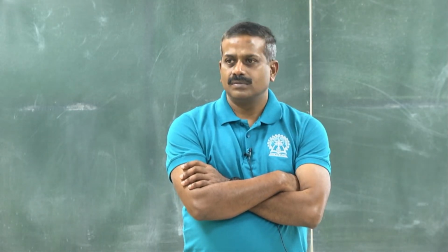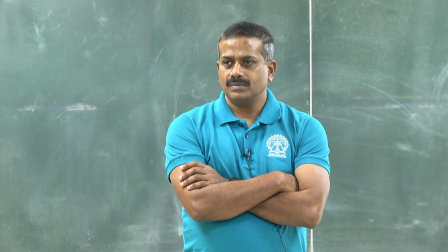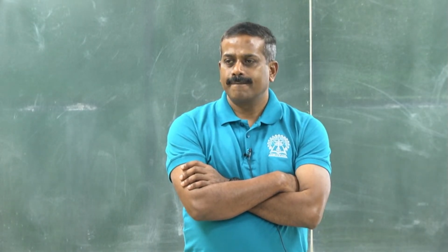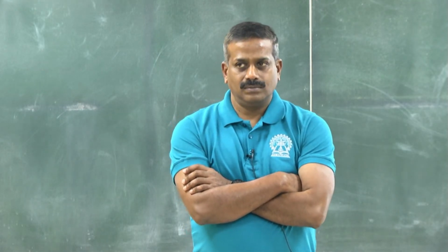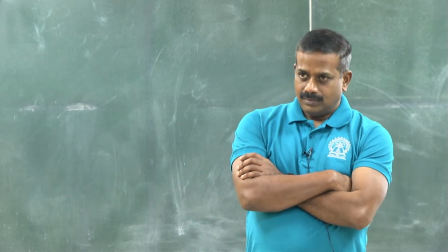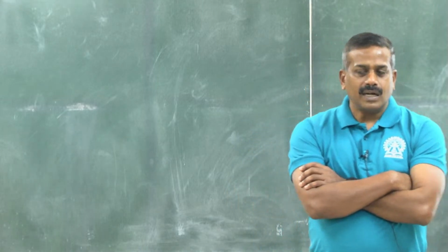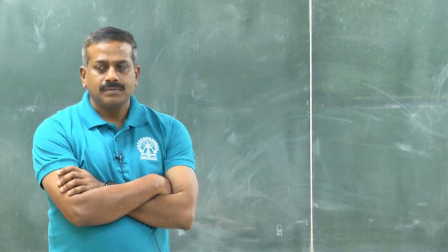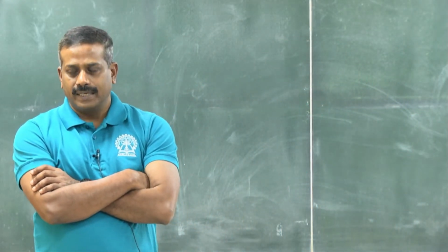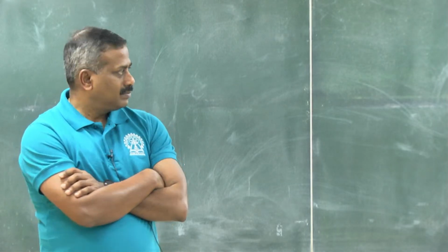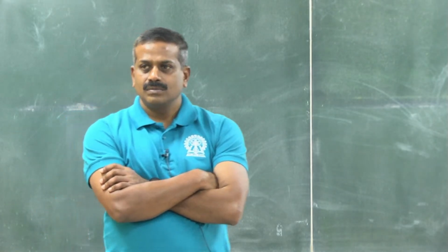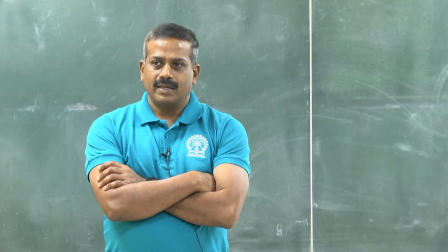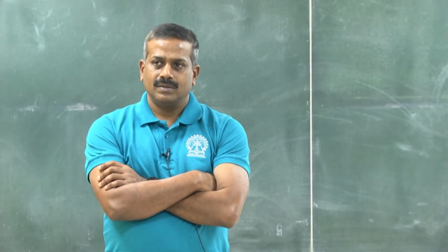And sir, when you are using this, we will get the Young's modulus. And how will you correlate that to mean porosity? Like for a porosity, we'll get a Young's modulus. And how will you correlate this? We are doing uniaxial compression. Then we will get the Young's modulus. Then we'll get a stress corresponding to strain. Then we'll correlate. We'll get the mean porosity from this.